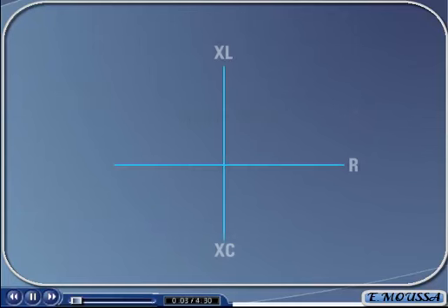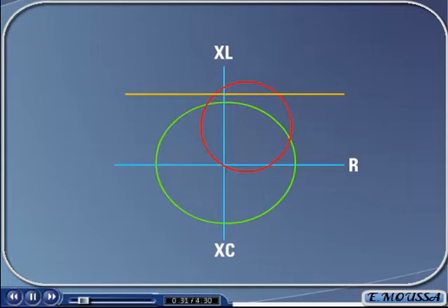To program distance relays, you need to configure the impedance of the line, where any impedance less than this value will indicate a faulted line. This is done in modern distance relays by creating zones of operation on the RX diagram. If the impedance calculated at the point of measurement of the power system ever falls within this zone, the relay will trip. These zones fit into the following operating characteristics: an impedance zone, an admittance or Mho circle zone, a reactance zone, a resistance zone, and a quadrilateral zone.